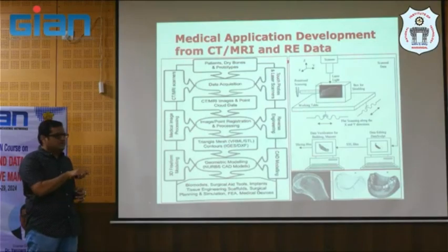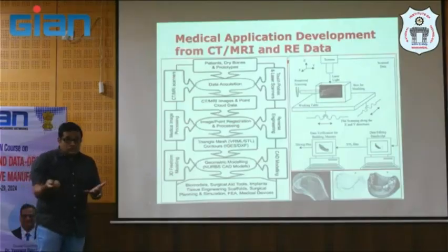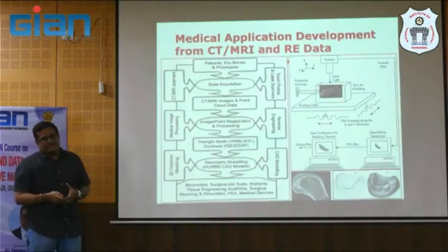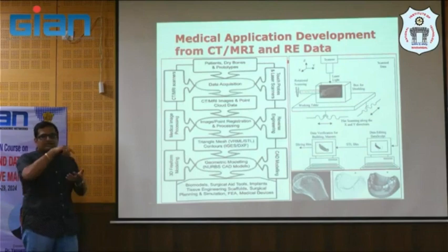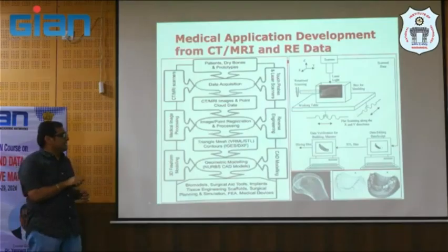Or even in the case of dentures, you are trying to get the outer surface. In that case, go with any 3D scanner. Normally you use a 3D digitizer or 3D scanner, which can capture in terms of point clouds, and you fit those points like triangles, in this case STL, and you fit a surface or a solid. So your job is done, right?